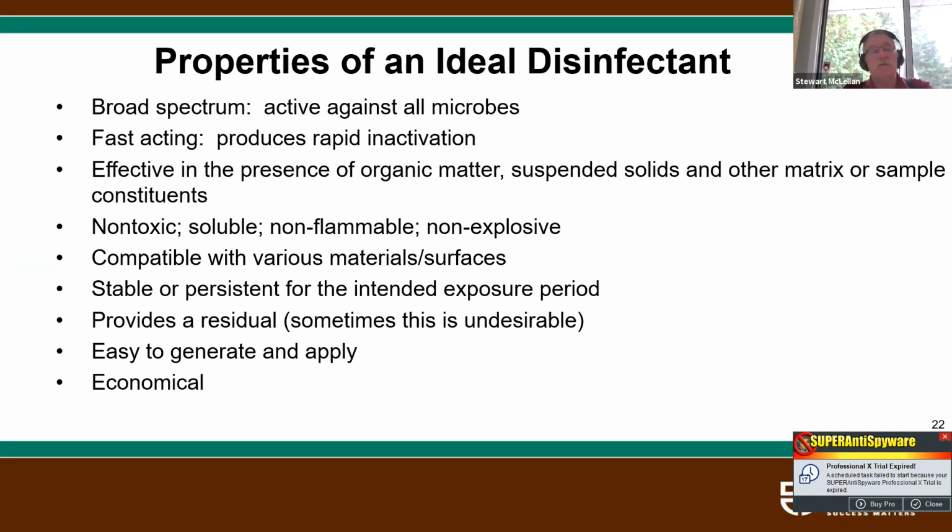But you can also have too high a residual, and then you can get odors and taste associated with the water. And you wouldn't want to discharge treated water to a surface water body with too high a chlorine content because of its impact on the native biota. You want it to be easy to generate and apply, and of course economical.